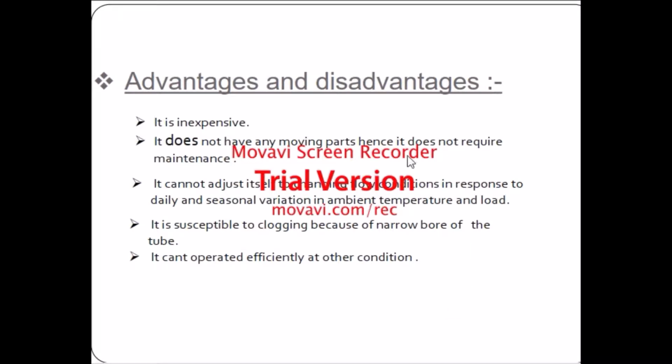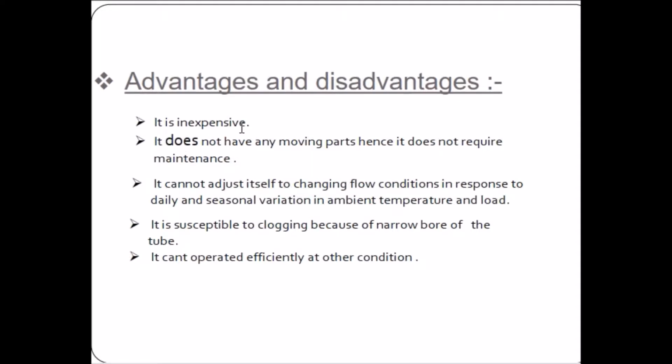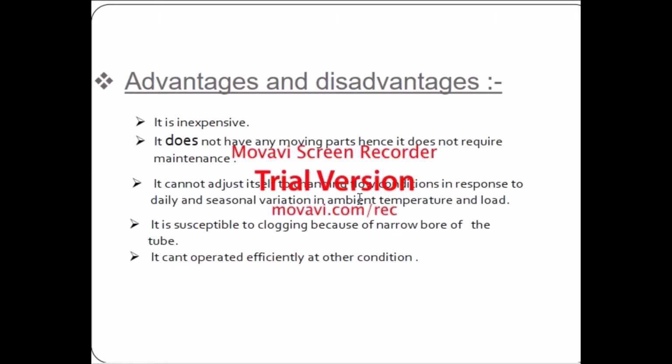Advantages: the first, it's inexpensive, correct? It doesn't have any moving parts, hence it doesn't require maintenance. Okay, very good. Disadvantage: it cannot adjust itself to changing flow conditions in response to daily and seasonal variation in ambient temperature and load.